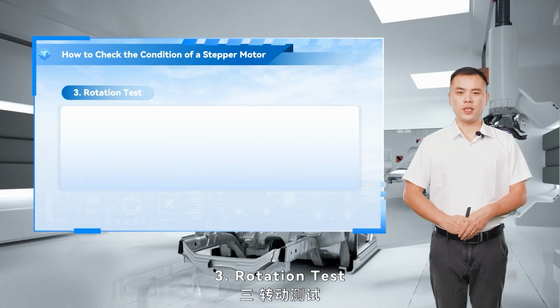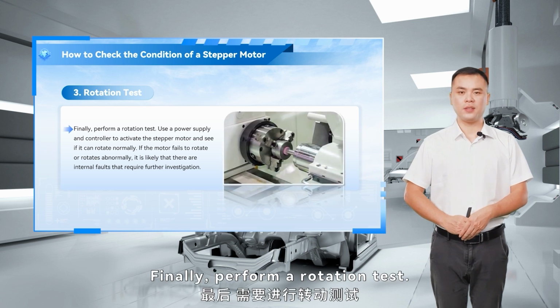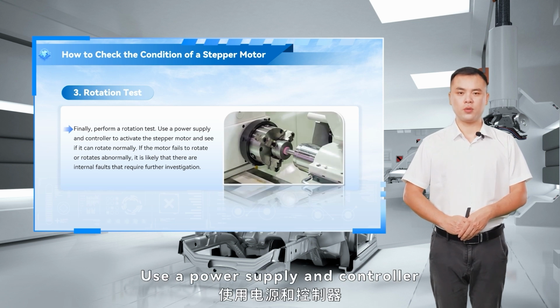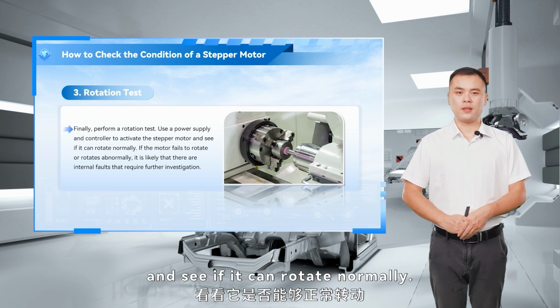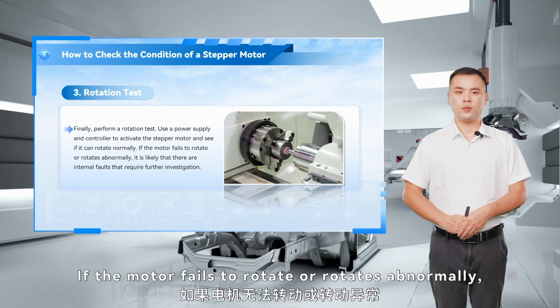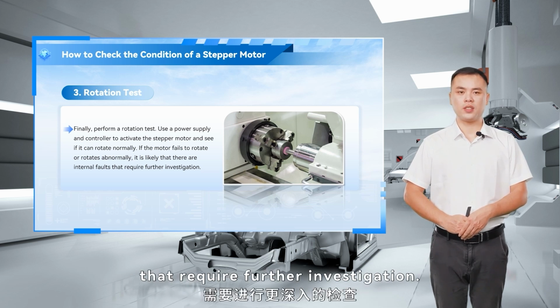3. Rotation test. Finally, perform a rotation test. Use a power supply and controller to activate the stepper motor and see if it can rotate normally. If the motor fails to rotate or rotates abnormally, it is likely that there are internal faults that require further investigation.